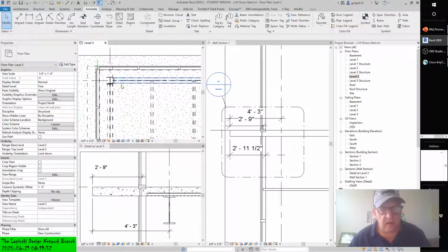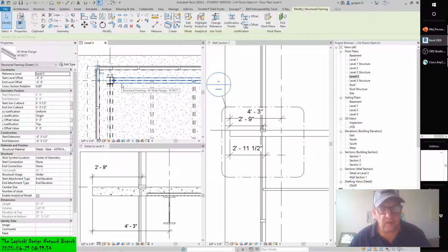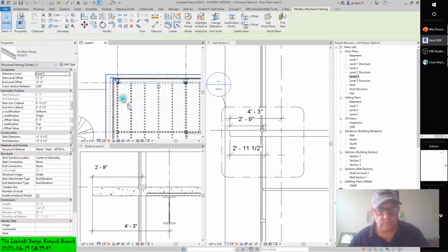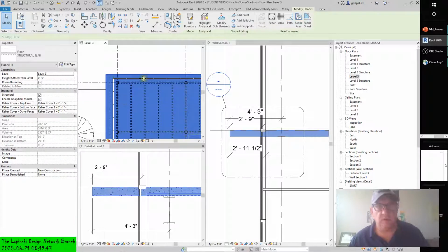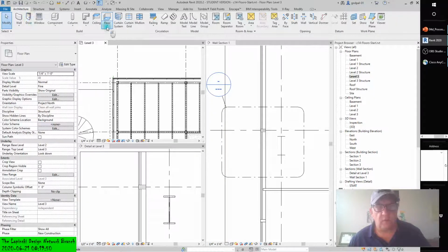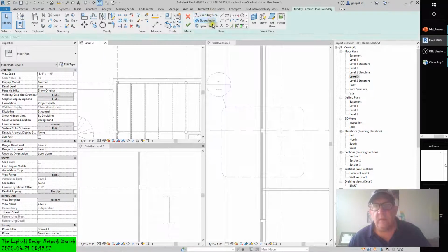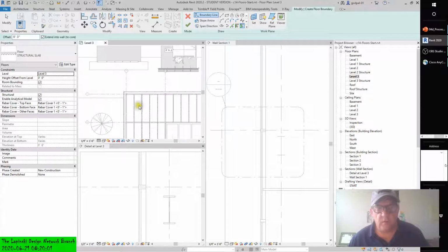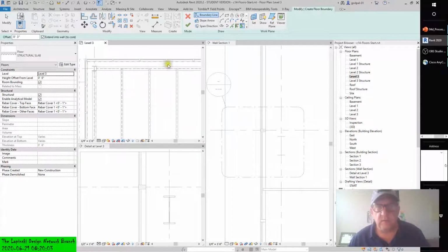There we go. All right, so as you can see, here's the W18 by 71 structural member. When we're creating floors, and I can delete the floor, we could go back to our architectural tab, structural floor, and we picked walls yesterday to define the boundary line. We could pick structural supports, add sketch lines based on existing structural walls and beams. So there's nothing saying that I can't